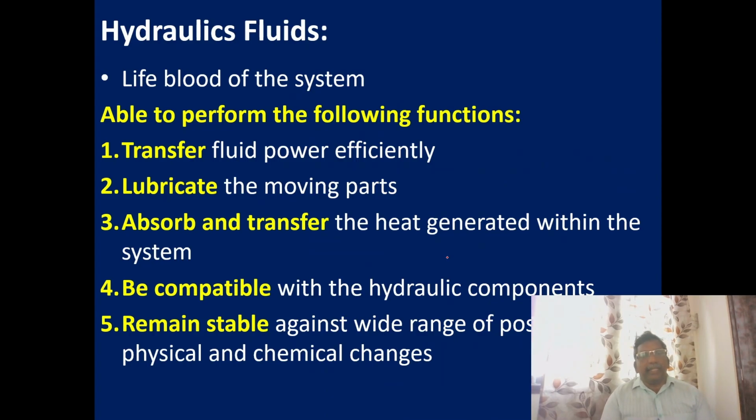We use hydraulic fluid. It's the lifeblood of the system. When we choose this hydraulic fluid, the following functions we have to maintain. For example, we need to transfer fluid power efficiently. Then there is no separate lubrication, so we have to lubricate the moving parts, then absorb and transfer the heat generated within the system. It's a high power, high pressure system, so we have to absorb the heat as well as dissipate the heat.